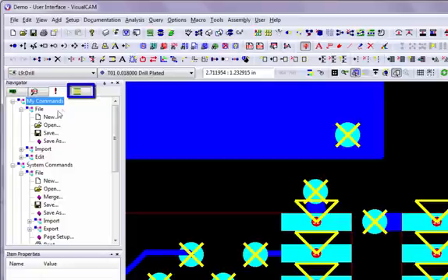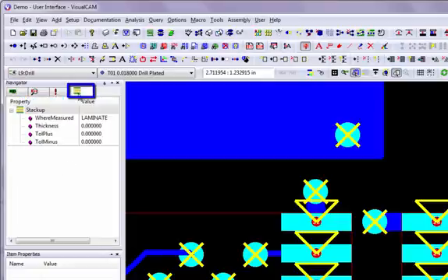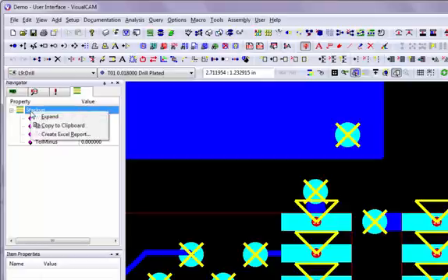The fourth tab is the detailed stackup information, as imported from your IPC 2581 file. To see a graphic representation, right-click anywhere on the stackup and choose Create Excel Report from the menu. For more information about the stackup generator and how to format your chart, see VisualCAM's Stackup Report Generator Guide. That's a lot of information on the navigator, but I wanted to show you how powerful and useful a tool it is.